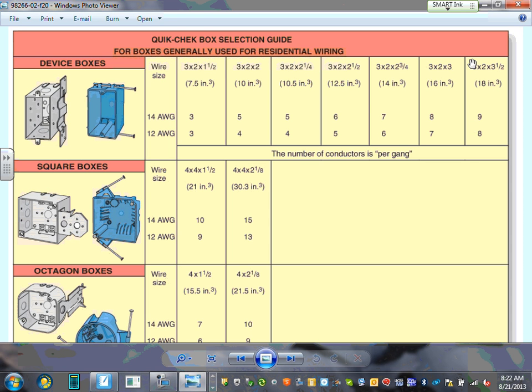When the inspector walks around, guys, rough in, they look at the box. Based on how deep the box is, they can tell you easily, oh, this box is crowded. How do they know? From these sheets. It's crowded or not crowded. And of course, there will be a device yet added. So that's how we use this one.